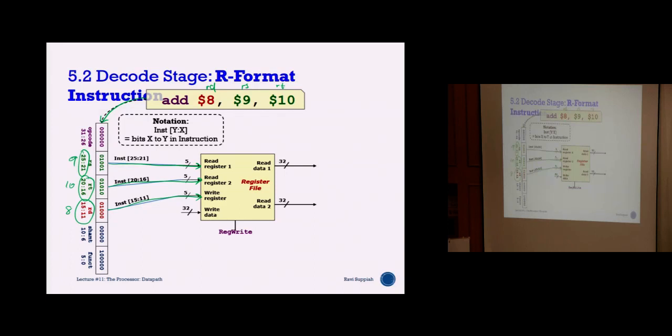So if I say 8 registers, it means 2 to the power of 3, correct? That means I only need 3 bits. So if from 32 registers I scale down to 8 registers, it means from 5 I go down to 3. That means I save 2. So for 3 registers I save 6.